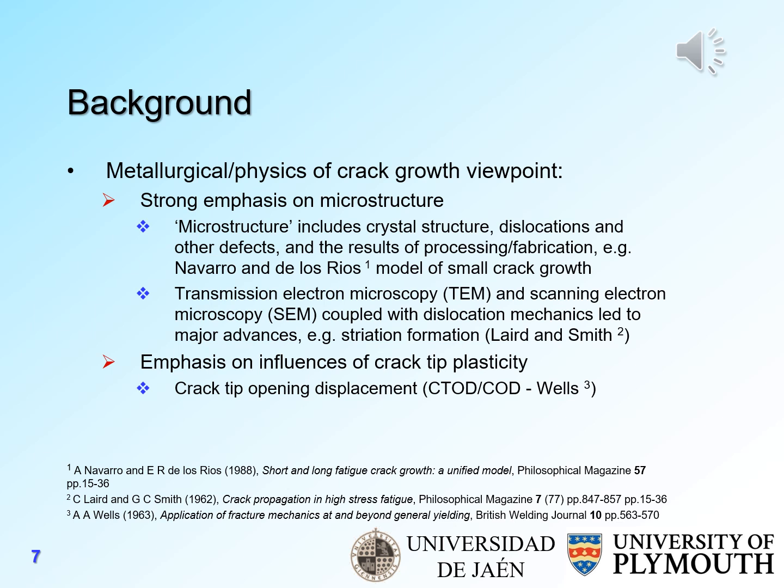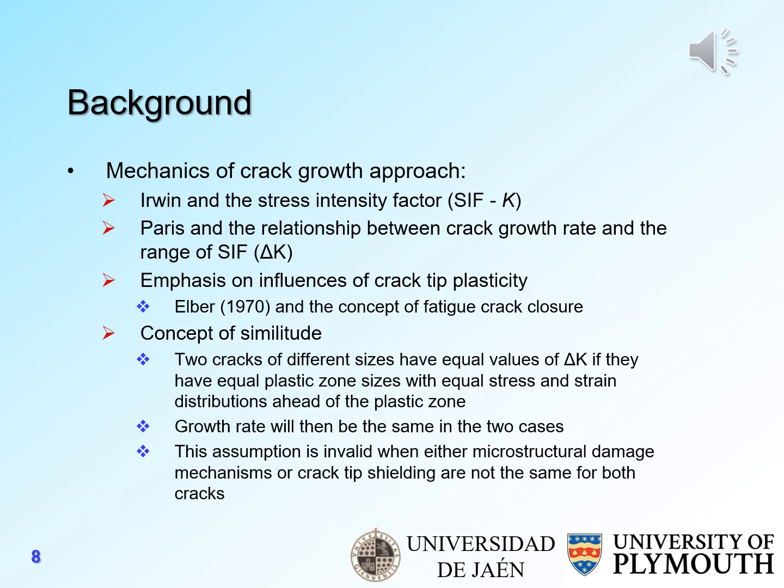There's also, of course, an interest in transmission electron microscopy and scanning electron microscopy coupled with dislocation mechanics. And that led to major advances, e.g. striation formation and in the science of fractography. And there was an emphasis perhaps on influences of crack tip plasticity, for example Wells at the Welding Institute and the crack tip opening displacement.